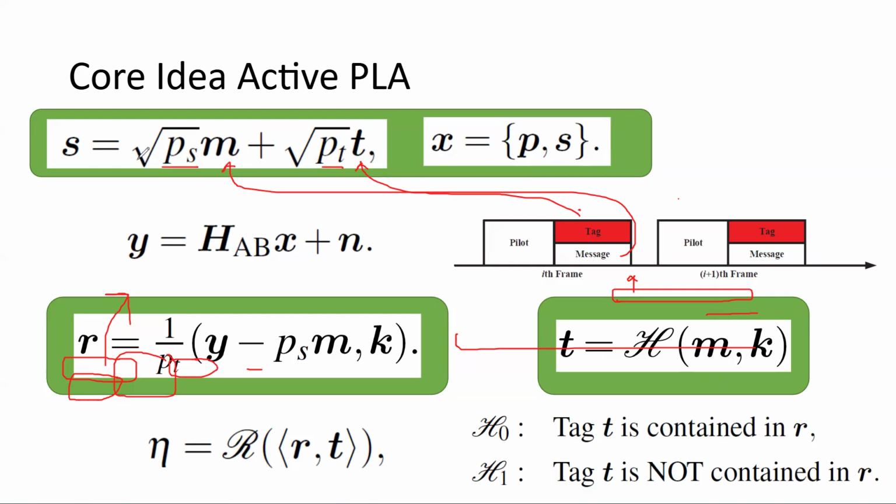Why do we take the square root of B_S and the square root of B_T? Because here the signal is written as an electric signal. If it's power, we take the square root of it so that it becomes like current. So the equations here are always written as electrical signals, not power signals, which represent either the voltage or current.